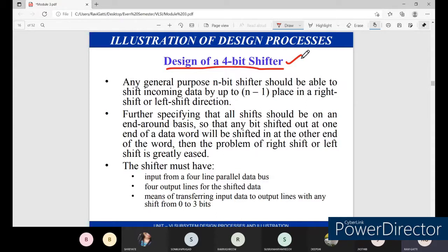Okay, so if I want to do division, what should I do? If I want to divide the given digital data by 2, I should shift the LSB to the right side. If I shift toward the right side, it will act like a divider. And these shift registers play an important role, especially in memory mapping or the design of memory processes.